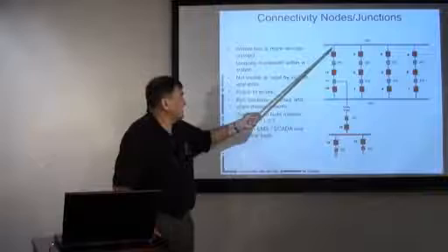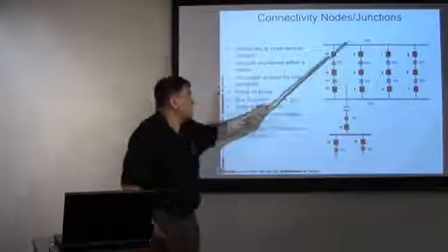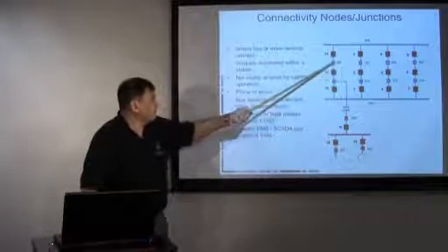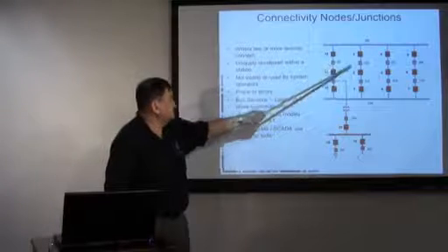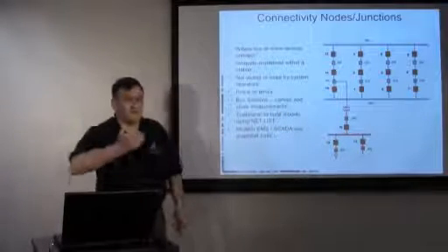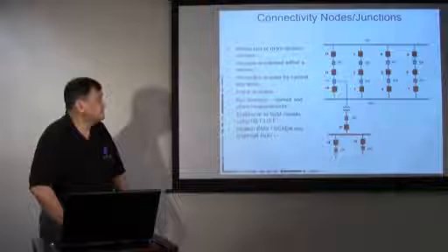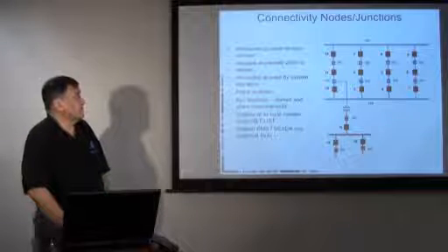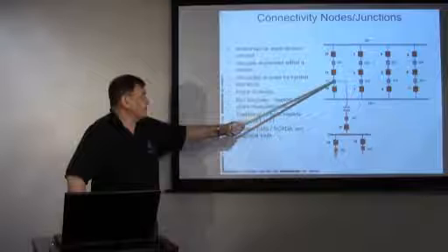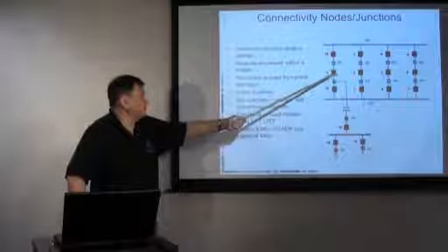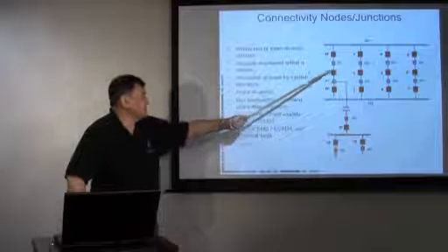So things can connect together through a bus section like this, or if we don't have a bus section, we introduce a connectivity node or a junction, and we have to uniquely give those names. And so we would say that breaker 11 has connections, a from node and a to node. So breaker 11 goes from connectivity node 211 to 221.